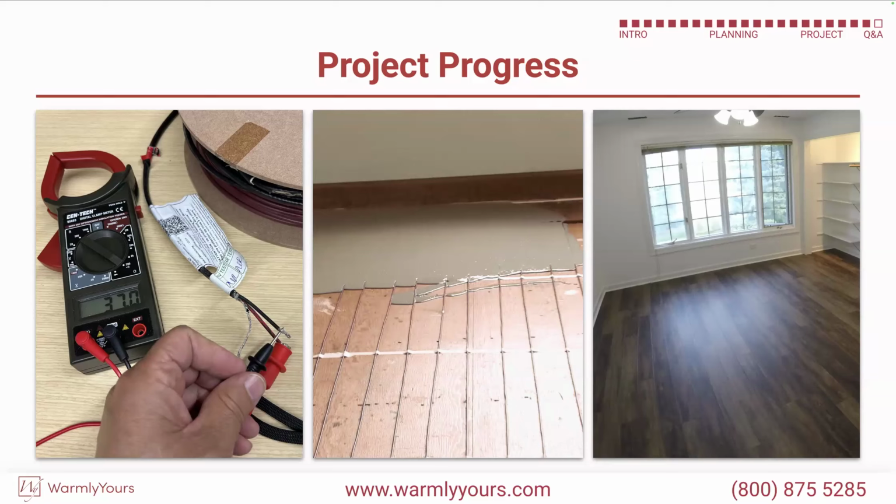And there's the ground. Now, another big question we get all the time is, where do I attach this ground? There's no ground terminal on the thermostat. Well, this ground gets tied directly to the house ground that's in the box that the thermostat's going to be in. So that's where that gets attached to. It doesn't attach to the thermostat. It attaches to the house ground in the box.